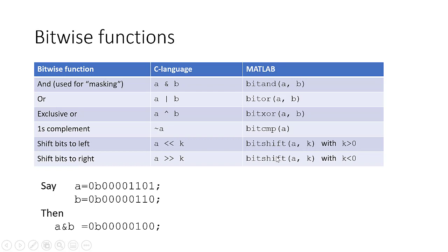So let's take some examples here, bitwise AND. Let's say that we have A given as this and B given as this, and we want to know, what is A AND B? Really, you just go bitwise. 1 and 0 is a 0. 0 and 1 is a 0. 1 and 1 is a 1. 1 and 0 is a 0. And then, of course, these all are 0, 0, so they're going to be zeroed. So this is the result.